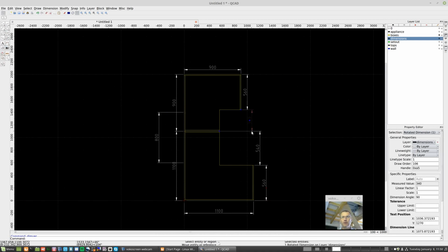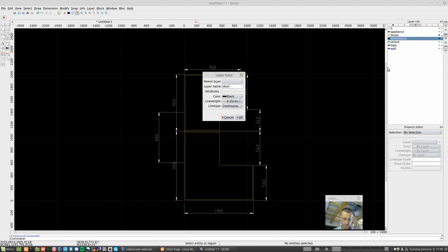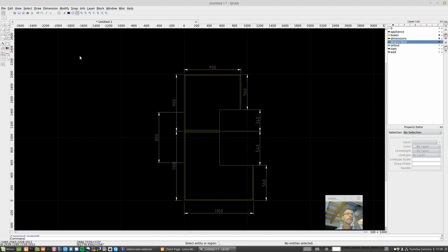And I actually might change this so it lines up with that. So I have some consistency. Alright, so I might make another layer for doors. Let's just get that rolling. Plus face. That'll do. Make that one maybe, I don't know, orange? Cyan. Yeah, orange is good enough. Let's do that. Okay. Right, so what we need first, a common arrangement is to have, draw parallels. Common arrangement is to have bifold doors in the corners. We need that changed to 16 or 18, whatever your door's thickness happens to be.